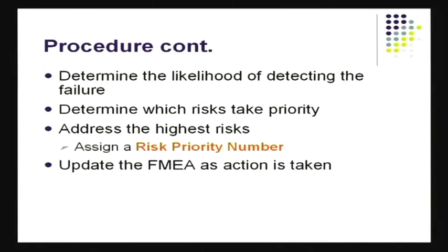You multiply these three quantities, which are the probability, the impact, quantified, and the detection capability. If you multiply these three, you'll end up with something called the risk priority number. If detectability is low, obviously it's more serious. So you'd like to give it a high rating because it's got poor detectability. When these are multiplied together, you end up with the RPN, the risk priority number. A risk priority number basically helps you to prioritize the different actions which this particular design deserves.